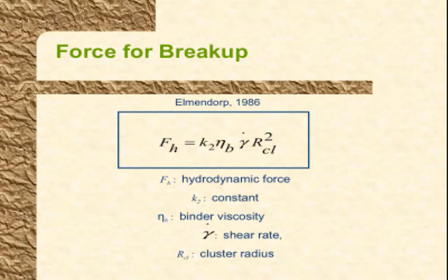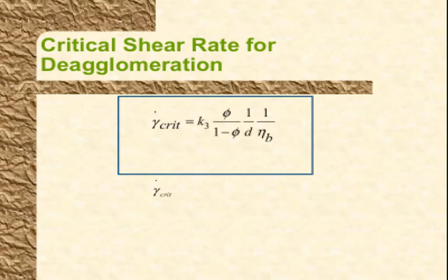Yes, but the thing is, for the force that is applied by the machine to be transmitted through the liquid onto the cluster, the higher the viscosity, the greater the conversion of the machine force into force that acts on the particle to break it apart. So they're competing requirements. You need a high viscosity to break down clusters, but a lower viscosity will allow you to distribute the particles more evenly.